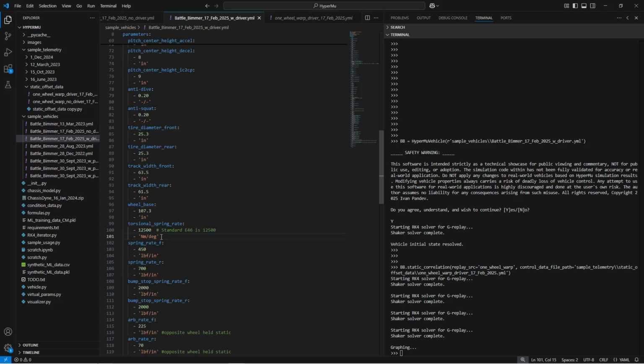But it's impractical to measure how much of that stiffness has been lost due to age, miles on public roads, miles on race courses, and various modifications cutting into the unibody, such as fender clearancing. Our inability to measure this accurately also contributes to the error. So the vehicle model defaults to the factory original 12,500, but this is an educated guess.